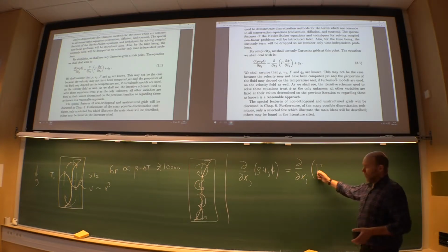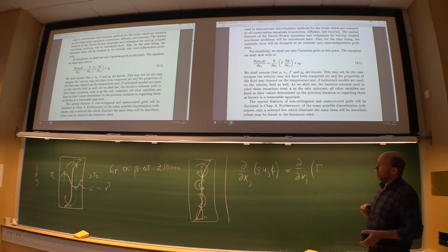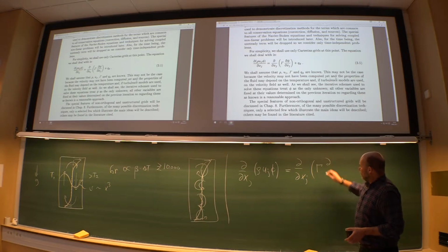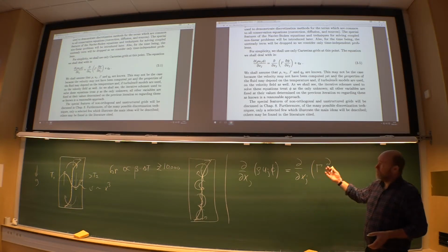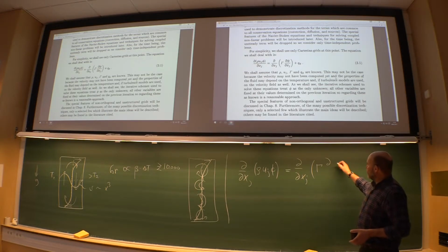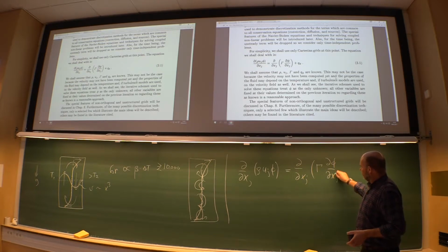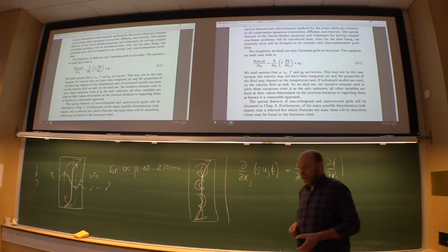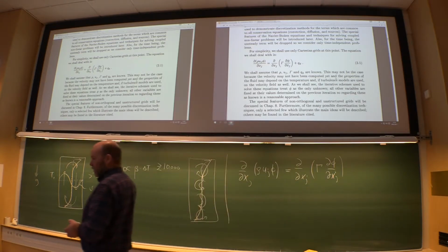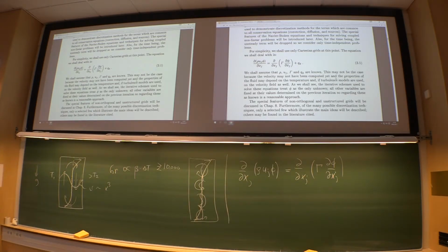Think of it as viscosity, kinematic viscosity, if you want to have some physics into it. But it could actually be anything. Temperature here, it would be conductivity and so on. So a diffusion coefficient. And then another derivative, like that. And then even a constant, if you like. So typically a model equation for the Navier-Stokes. So of course, the phi there is going to be a velocity.